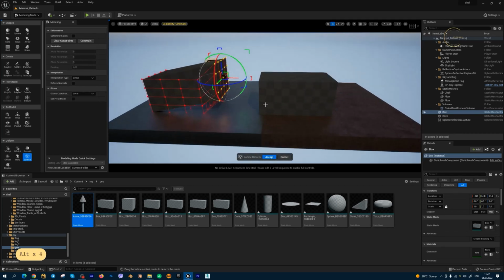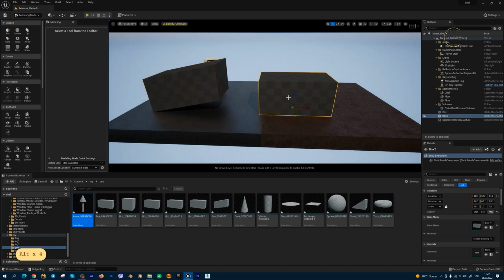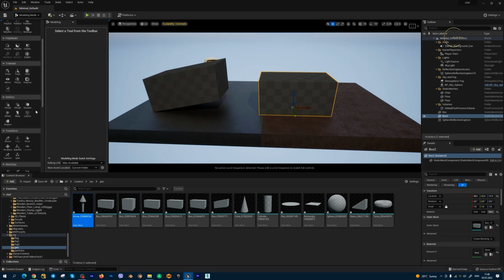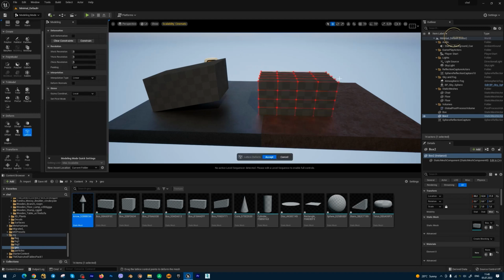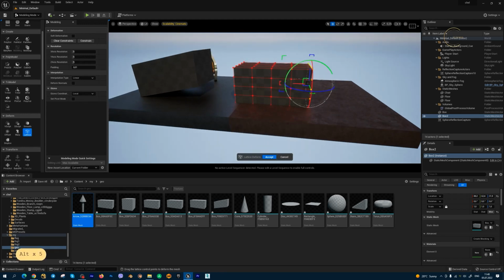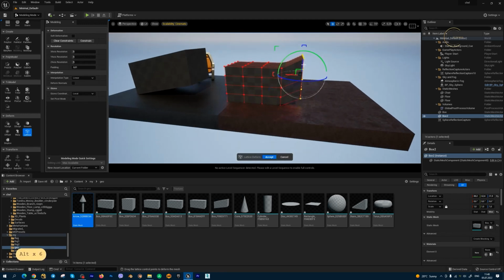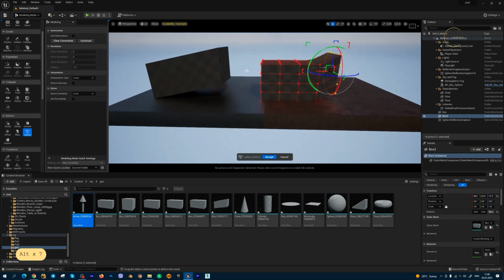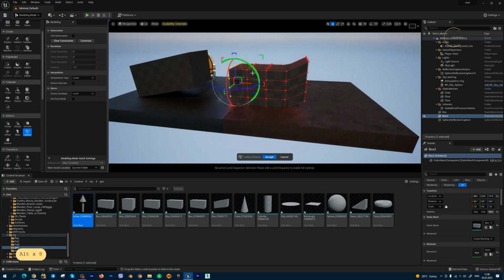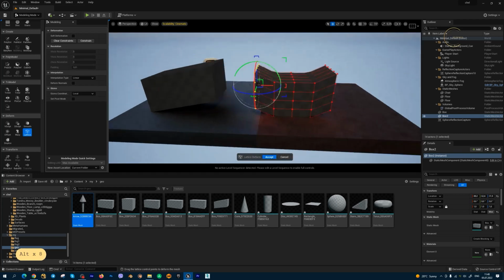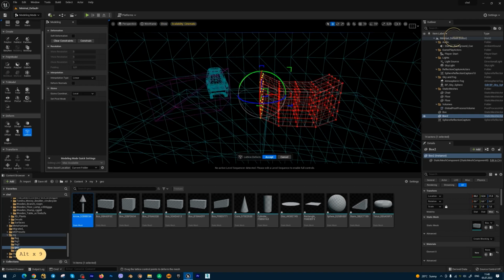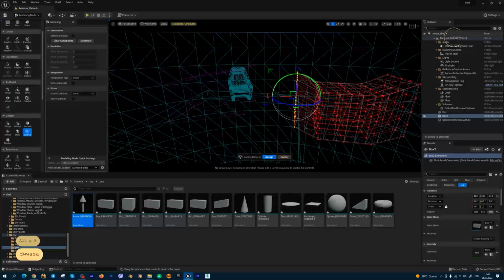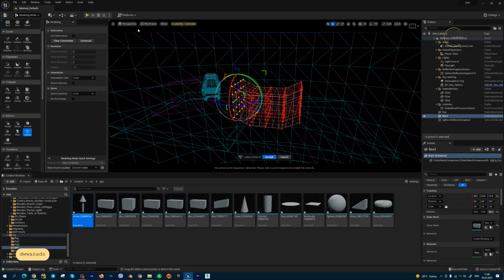not interesting result. But if you use the same lattice instrument in the viewport window for this high poly mesh, you can select your vertices and create more complex geometry with this type of mesh. When you go to wireframe mode, you can see the difference between these two types of mesh.